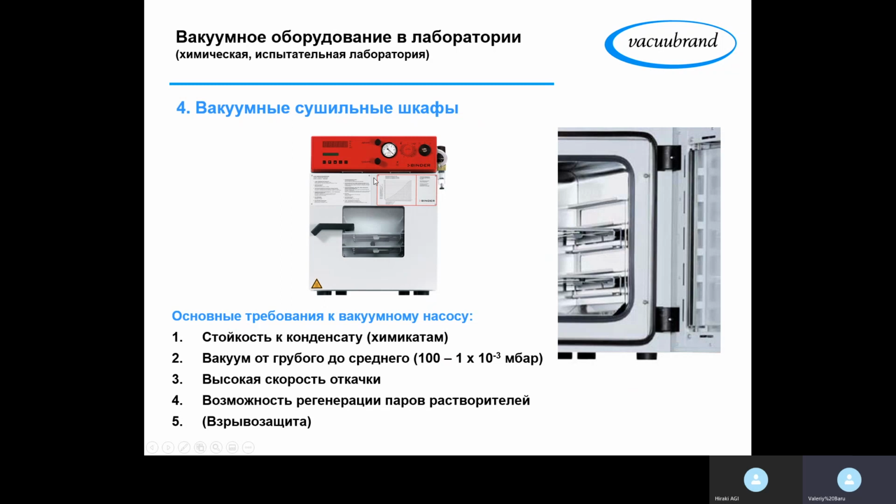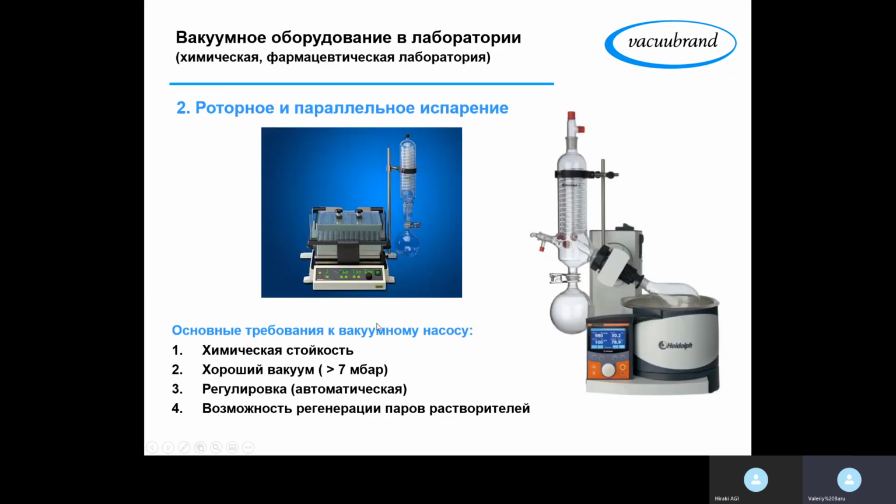In some cases, for this kind of application, we may also need an explosion proof pump. Actually, for the rotary evaporators, it is not marked here, but in some cases we need an explosion proof pump.